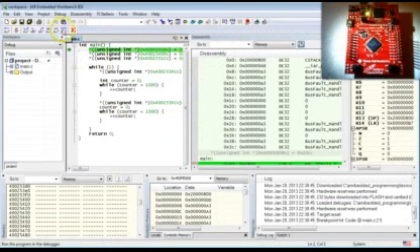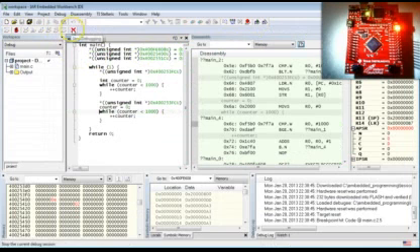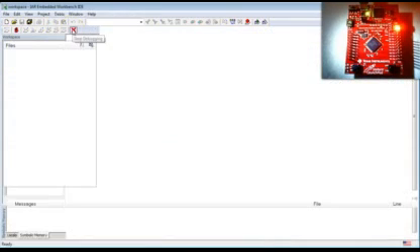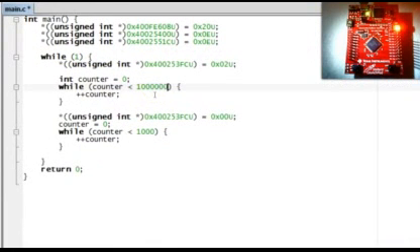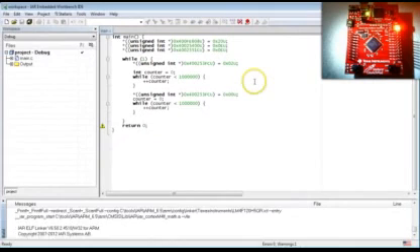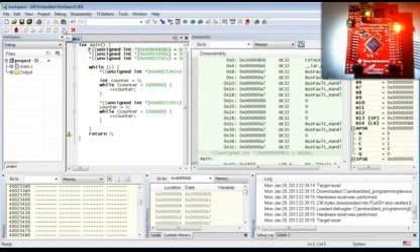Let's delete the breakpoint and run the program. Well, still seems too fast. Okay. Go back and increase the limit by another 3 orders of magnitude. Try again. And hey, it appears to be just right. The LED keeps blinking.